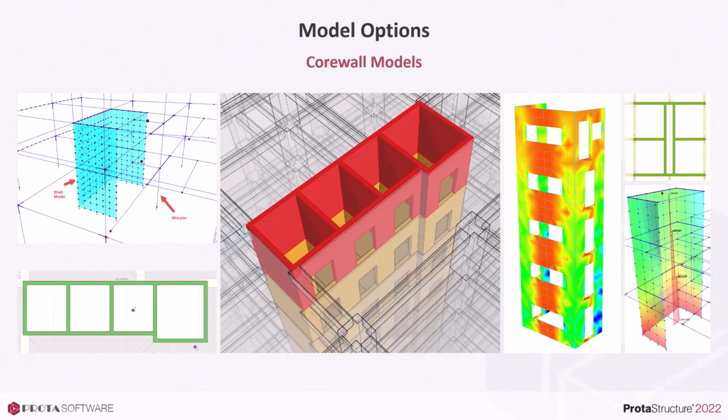Rectangular wall panels can be merged into complex core walls. Analysis, design, and detailing are done considering the combined section. Core walls are always modeled with shell members, regardless of the default wall modeling option, especially because of potential torsional behavior depending on the structural configuration.